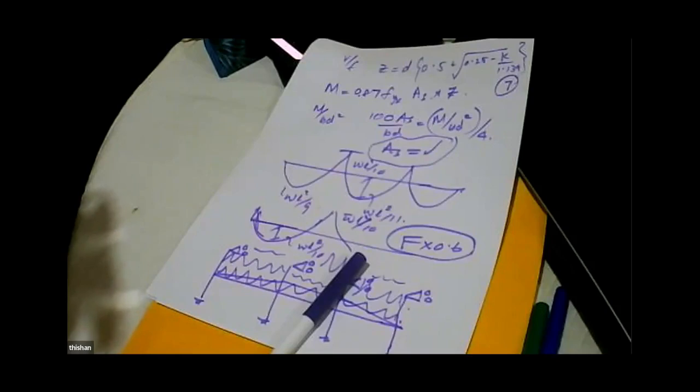If the load of the slab is distributed to beams as per yield line pattern, is it reasonable to curtail bottom reinforcement close to the corners of the slab? On the contrary, actually, in two-way spanning slabs, no engineer practices this in Sri Lanka, but there's something called the edge strip and middle strip. All the moments that you calculate based on the yield line method are applicable only for the middle strips. End strips is not applicable. End strips have nominal reinforcement. No engineer in Sri Lanka practices that, but by practicing the edge strip, middle strip method, you can save a lot of steel in a slab.